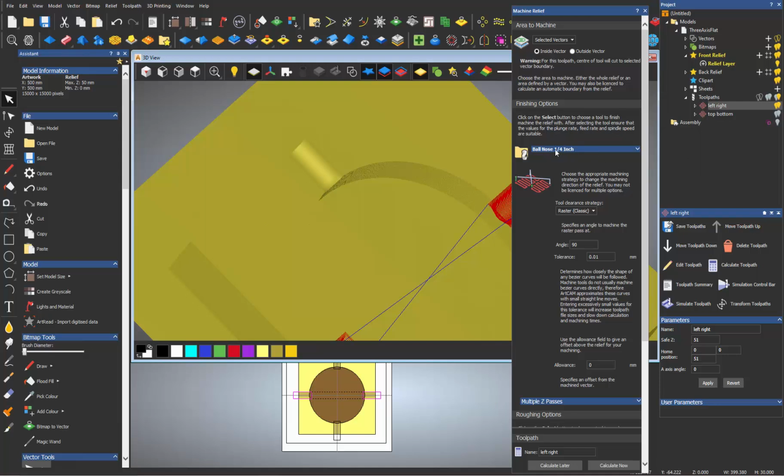I'm actually using a 1/4-inch bit to come in here, so there's not a lot of tool contact, because I don't know the diameter of those. Those might be just 1 inch. I don't know. But having a smaller tool go in there and do multiple passes on it will hopefully reduce catching and doing that chip out of the wood.